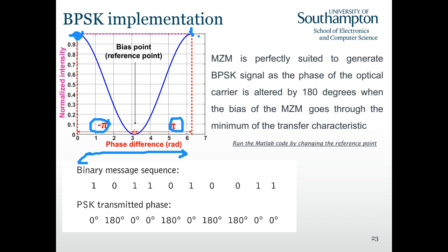So if you modulate the whole range of 2 pi by multiple amplitudes, then you can use phase to distinguish different logical bits, but they will have the same amplitude, right? So you actually modulate logical bits onto the optical phase.